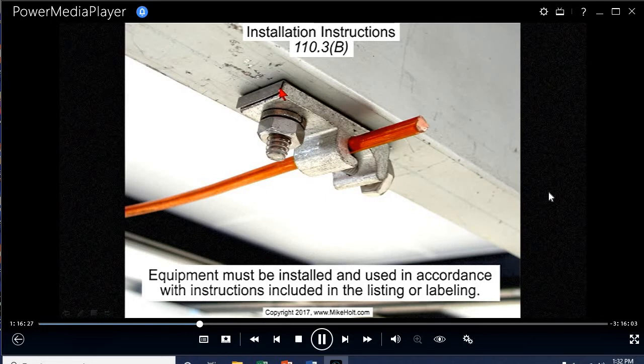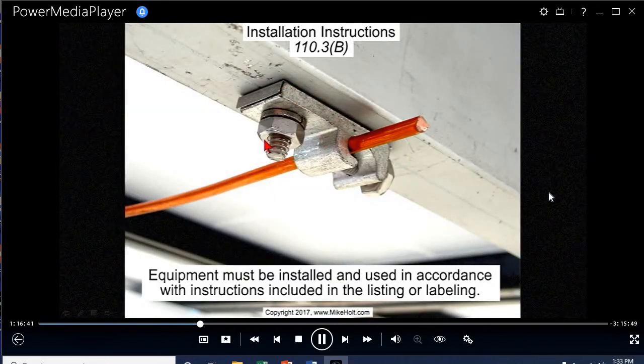It's a product designed so that when you bolt this down, it takes the anodized aluminum and breaks the aluminum bond connection, and then it breaks the bond on this particular fitting and this particular screw at a specific torque. That then makes this module bonded to this fitting, so that you can take the equipment grounding conductor and terminate it with a torque to make sure it's correct. You just can't take a lug and stick it on a piece of aluminum, because aluminum is anodized.